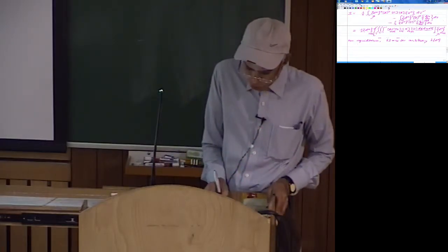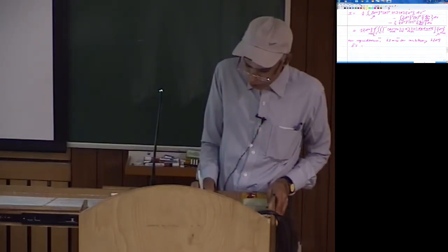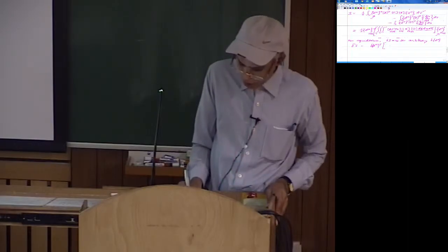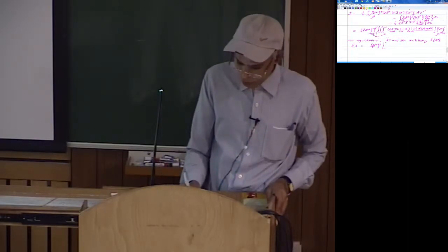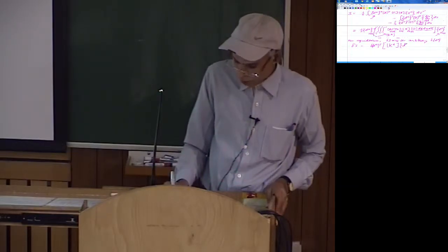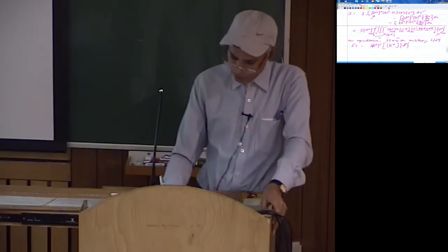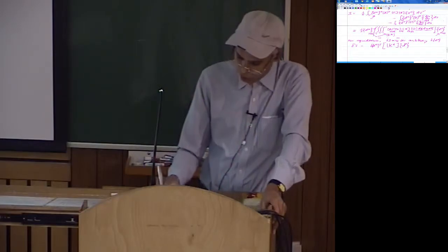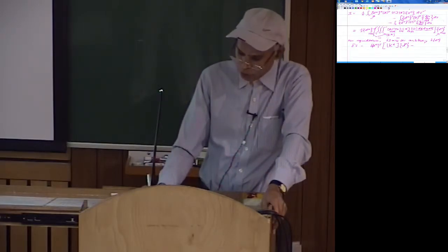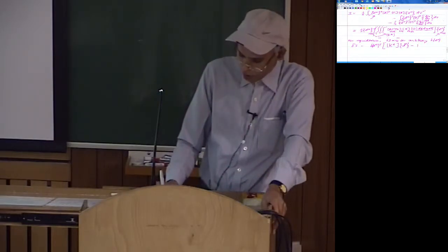So finally this delta of I can be written as delta of dE transpose, and what you will have here, let me call this entire thing KE, that is the element level stiffness matrix. Then this dE would be there, so this dE is left out, and similarly this delta dE transpose is taken inside. So let me call this quantity H transpose fBx, fBy, fBz as F external.